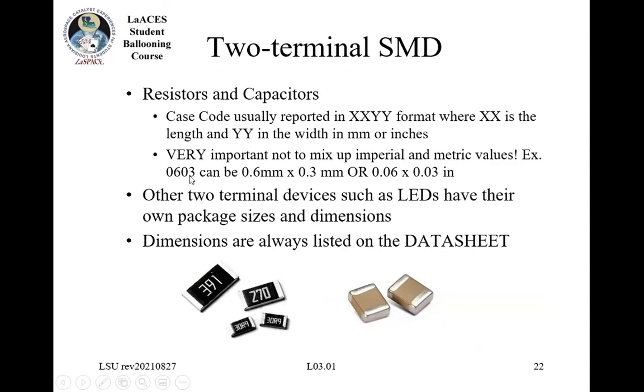You can go smaller than this to the 0402, but usually whenever you see those components, you send that board off to an assembly company, and they use pick and place robotic machines that will do all of the soldering for you. Then you just get the board back. So just keep that in mind.